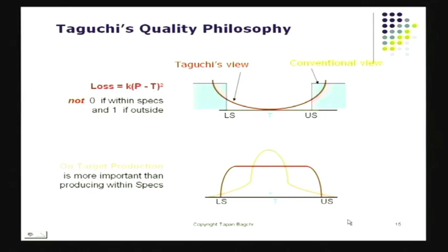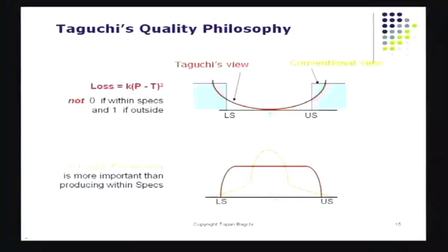The difference was these two types of what we call in statistics populations. The population of TVs produced in San Diego met specification, but did not lead to as much satisfaction in the house of the customer, as opposed to the Japanese TVs that were assembled such that they were smack on target when they're shipped. Those led to a high level of satisfaction and fewer complaints. Now this again highlighted the fact that when you're doing design or assembly, please make sure that the quality characteristics are as close to the target value as possible, which of course is determined by a process called QFD, quality function deployment.